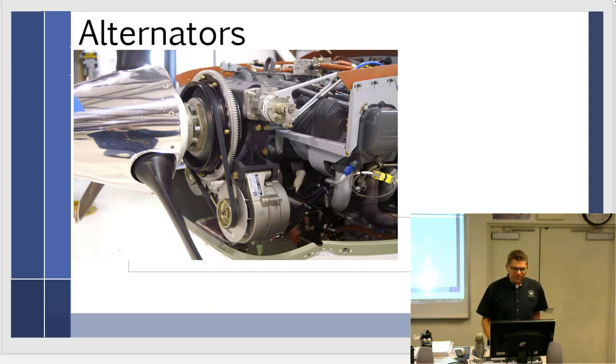But you know what people love to do, since we're on this picture? In order to change this belt, see that belt's about like that, and I'd say the propeller's about like that. How do you suppose they get that belt over and around the propeller? Cut it. One at a time. Take the prop off. The blades are this long. You cut the belt, put it around, and you melt it back together. There you go. So you've got to take the prop off to change that belt.